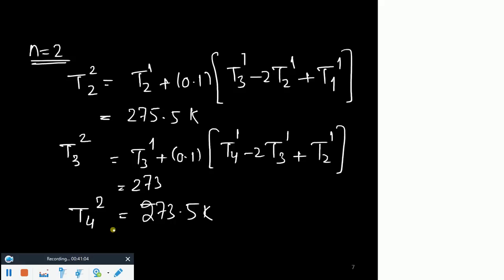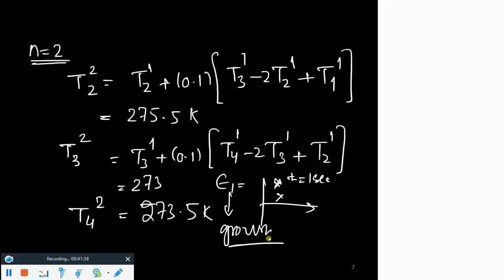For example, the analytical solution needs to be here. Let's say the analytical solution says that at time equal to 1 second, it should be here. And if you keep delta T very small and delta X very small, you would be somewhere here. So you can say your error 1 would be very small, right? But if you take alpha delta T by delta X square equals 0.1, for example, you may be here. Still it is stable, but this error has... now this is accuracy, this is not stability.